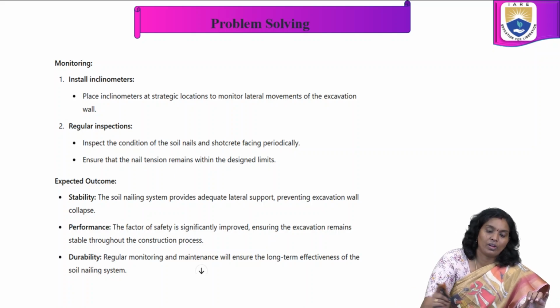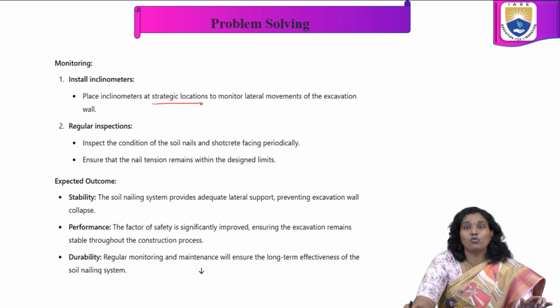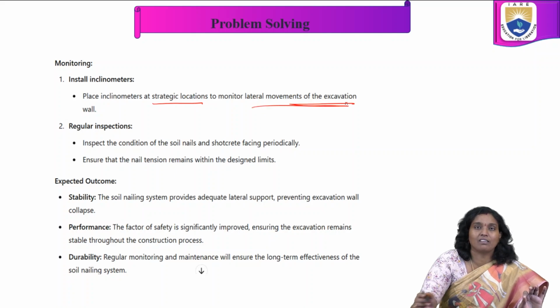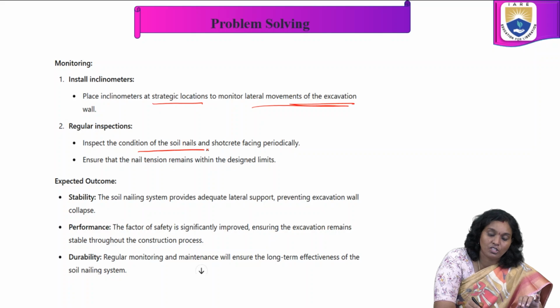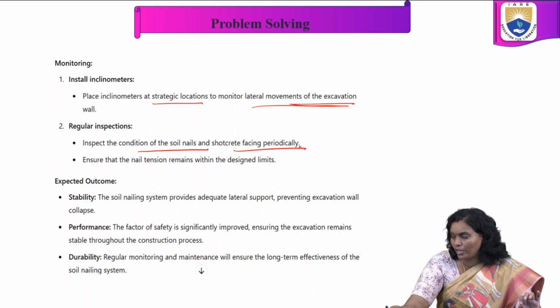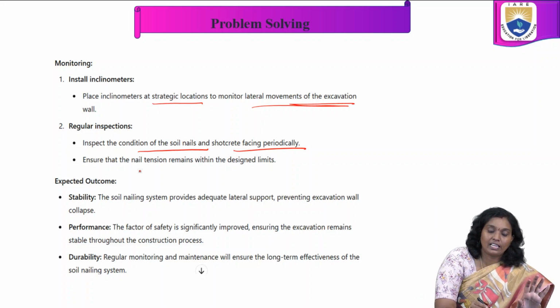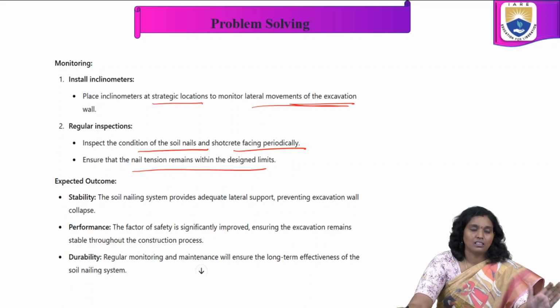Place inclinometers at strategic locations to monitor lateral movements of the excavation wall. For regular inspections, inspect the condition of the soil nails and shotcrete facing periodically. These inspections ensure safety, and we can understand whether the nail tension remains within the design limit or not.